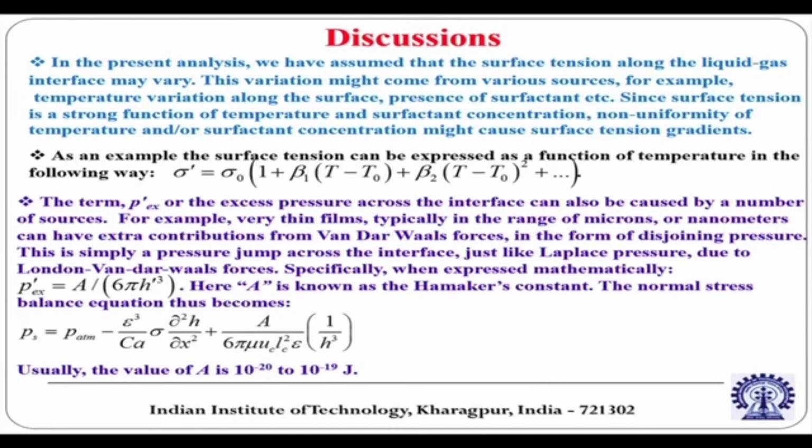These forces become important only when the film thickness becomes so small that intermolecular forces also play a dominating role. One typical way of representing it mathematically is this particular form. I mentioned a reference book where you will get the details of this variation, but to summarize, in a continuum calculation this scales as a parameter A by h prime cube.